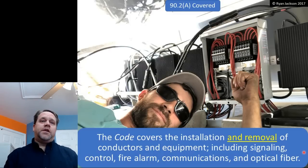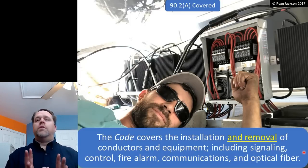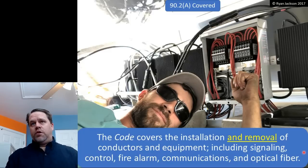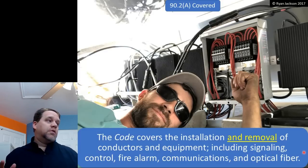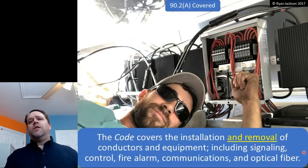But that's the only place that the code requires you to remove unused equipment. You don't have to remove unused EMT or 12 gauge THHN, MC cable, panelboards, switchboards, boxes. You don't have to remove any of that stuff. You just have to remove abandoned limited energy cables. But back to the topic.